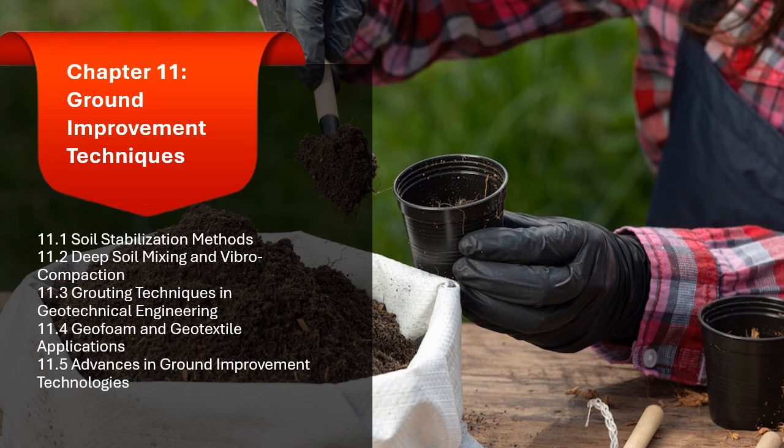1.5.5.1 Geophysical monitoring techniques. Innovative geophysical methods, such as ground-penetrating radar, GPR, and electrical resistivity tomography, ERT, are increasingly being used to monitor the effects of ground improvement techniques in real time. These methods provide detailed insights into the soil structure, allowing engineers to assess the effectiveness of treatments and make adjustments as needed.